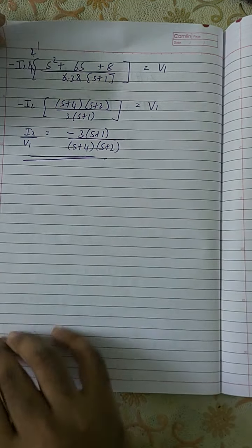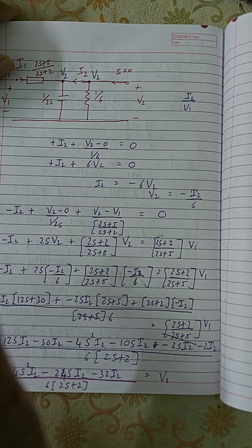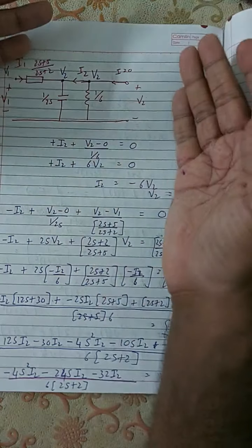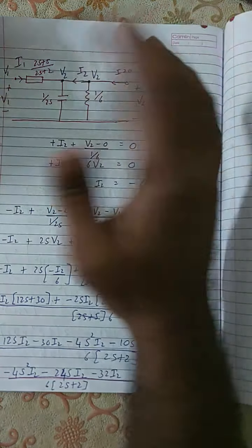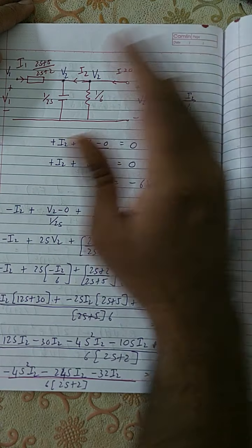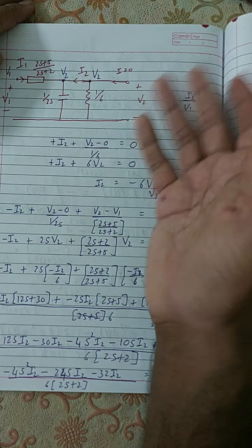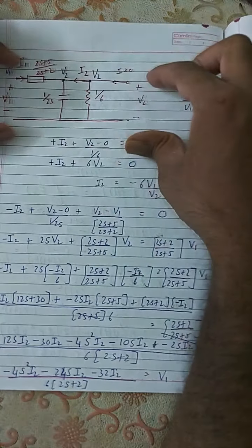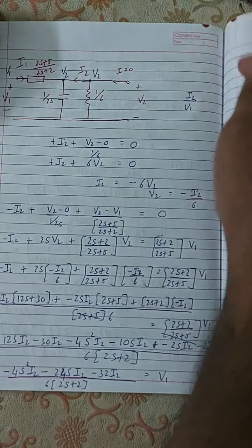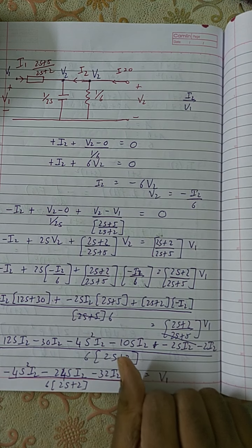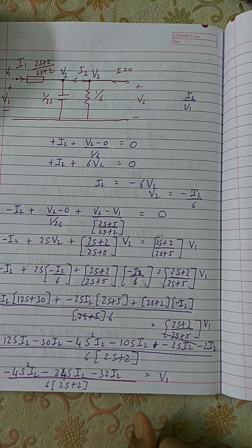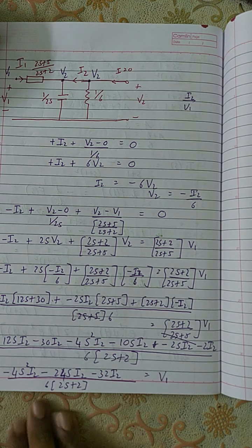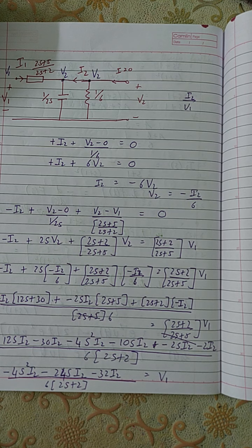So you see these kinds of questions, you can apply any method you want. The only thing is, don't make a mistake when you're applying the Laplace transform to the resistor, the capacitor, or the inductor, or wherever it is. That's all. You can apply Kirchhoff's voltage law or Kirchhoff's current law, but I prefer Kirchhoff's current law for these kinds of equations because the circuit is in ladder shape. So you can apply node analysis. That will save you a lot of time. Then the rest depends on your speed. As of now, it took me around 16 minutes to do this problem, if I'm looking at my time right. So this is it.